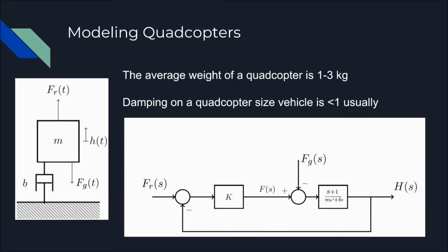Our system input will be the desired height, powering the rotors to control the force they exert and therefore the elevation. Along with this input, there is a loop relating elevation changes based on these inputs to regulate the speed at which the elevation will change. The direct output of our system will be the elevation of the copter. We have included a gain K in our system to allow the system to become stable within the closed loop. H(t) is the outputted elevation, Fr(t) is the force of the lift, and Fg(t) is the force of gravity.